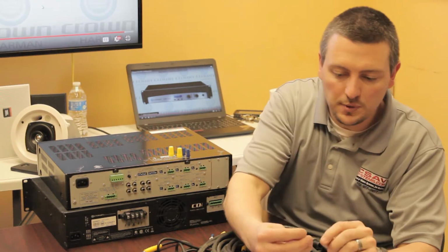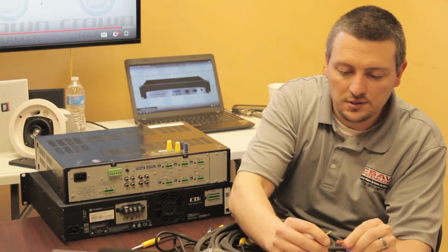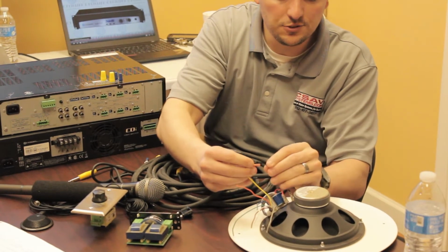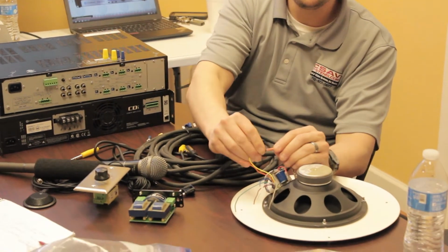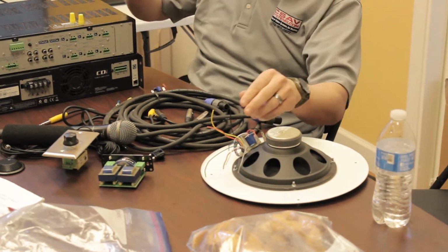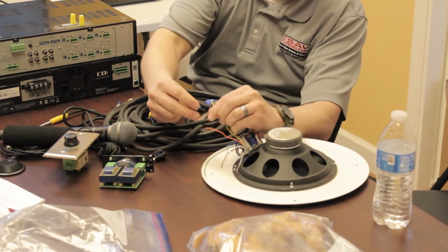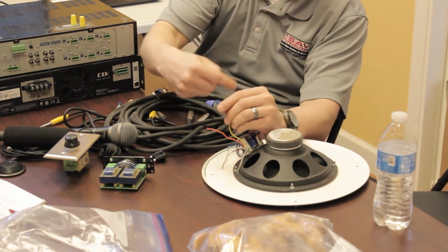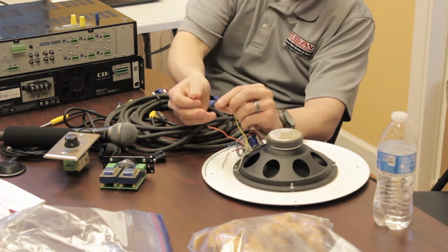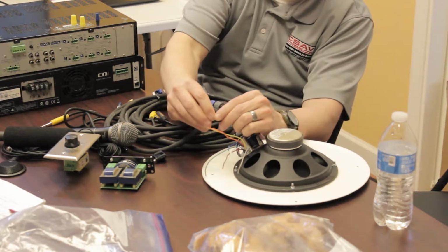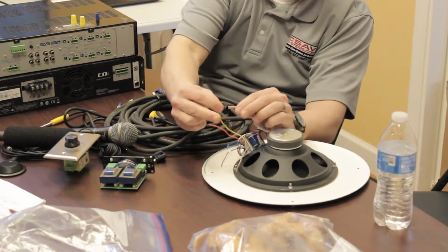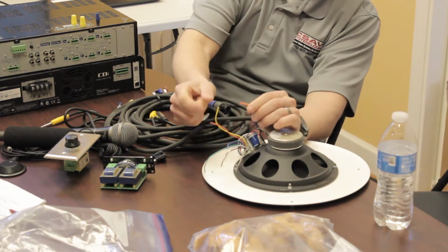If you're doing a splice, not with the speaker, but say you cut the wire and you're trying to extend it, especially if you need to tape something up, a big connection with two wires makes a much fatter tape wad. So you'd strip back about 1/4 inch, put it in both sides, and crimp both sides to make sure it's tight.